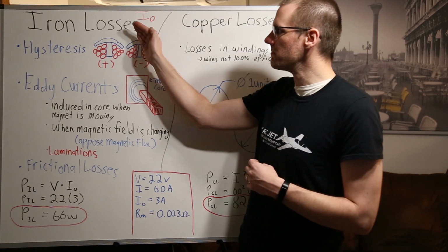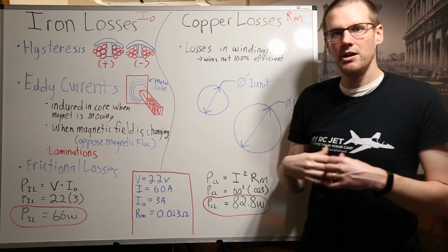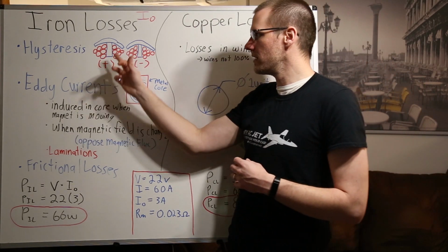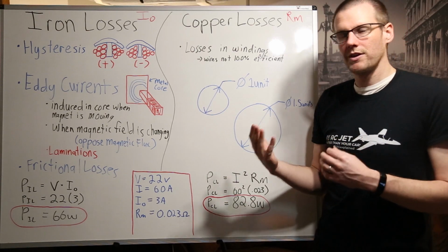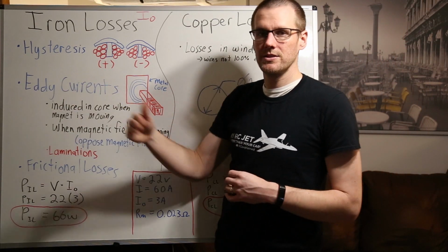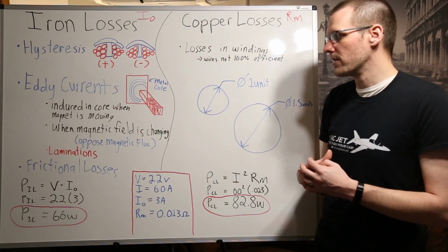This is happening as a magnet passes by the stator tooth. You're going to have these eddy currents being produced or induced in that metal material. This is going to create, in the form of heat, wasted power for us. This is in no way good to us. It's complete waste of energy when we're talking about that sort of thing.